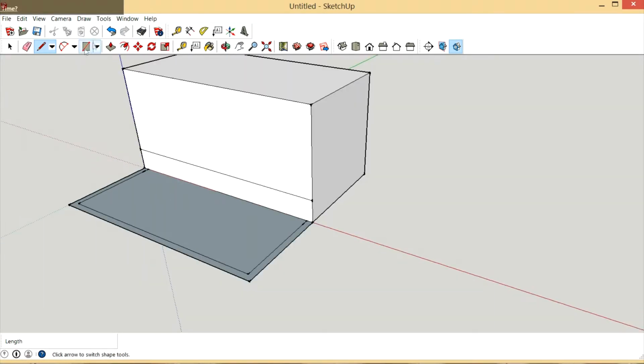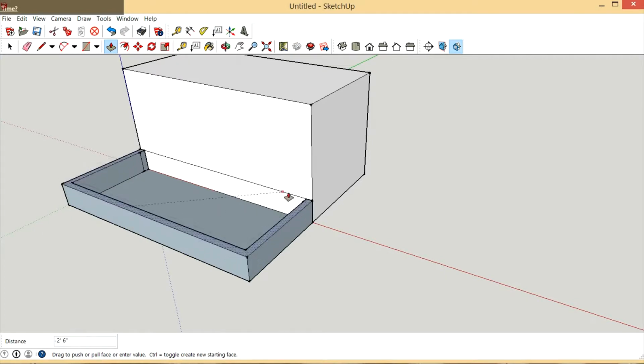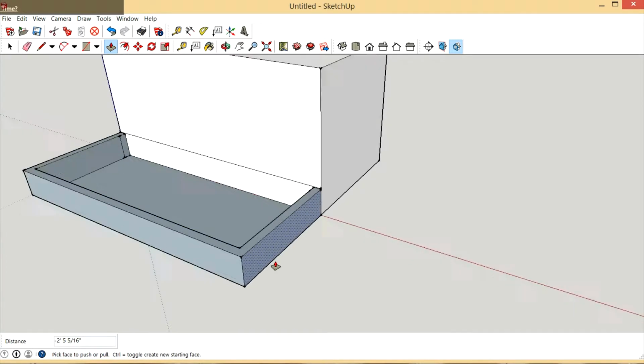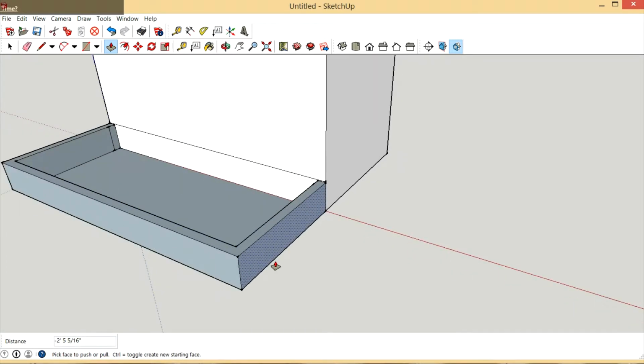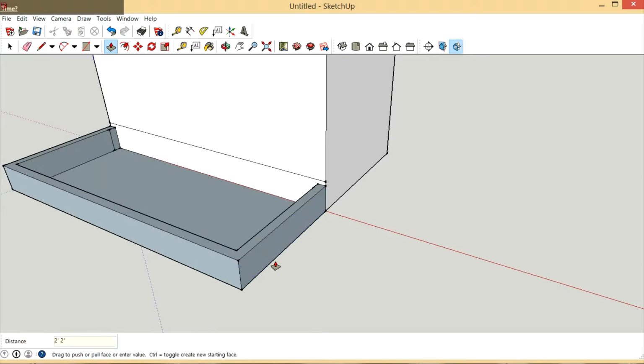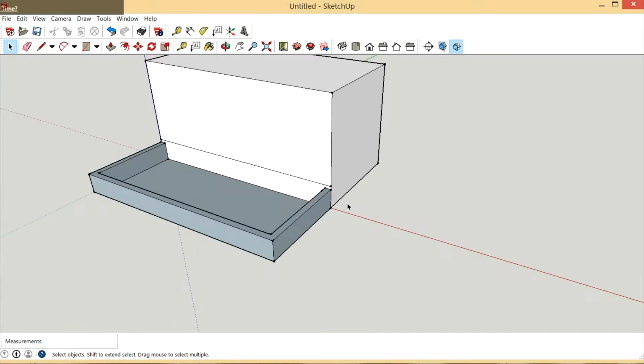And then what I can do is pull that up to here. Again, this porch is 30 inches, so we'll allow 4 inches. So we'll make this 26 inches. I'm just going to type in 26, and you can see how it lowered it back down after I entered the value. So there's our concrete block wall already that we have.